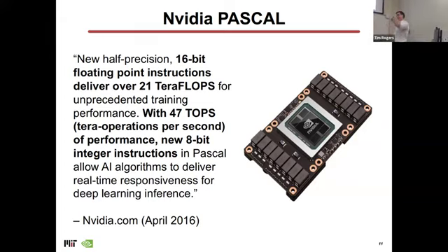And then they went to Ampere, where they supported FP8 and FP16. And now if you look at Blackwell, it's INT4 that the tensor cores support. Because why not? And then we also had to drop the F from FLOPS, because it's not a floating point operation anymore. It's a T, because it's a tensor op.